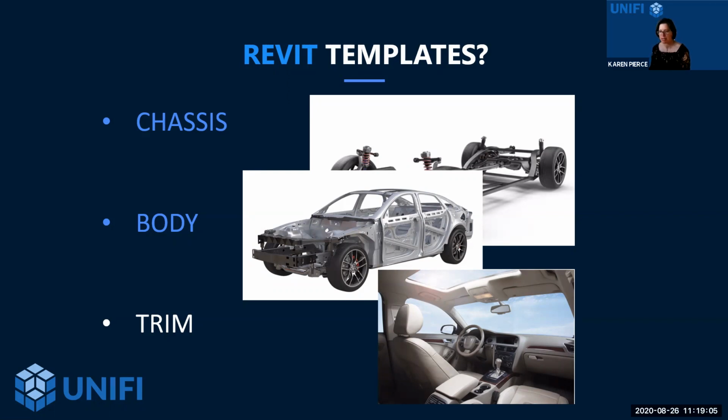And while I'm an advocate of keeping Revit files as lean as possible, Revit files tend to always get big on their own. You'll notice that when you have heavier templates that are really geared towards the content itself, you're waiting to purge the model till maybe halfway through the job or so, because you don't want to lose all of those starting blocks that you're probably eventually going to need. So what I'm actually going to show you is that there's a few alternatives you can tend to pursue.